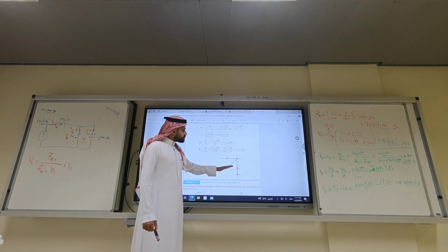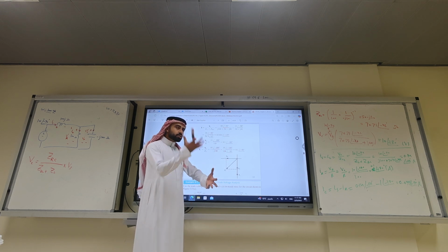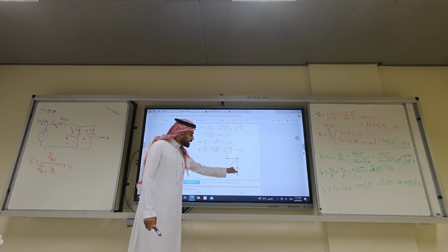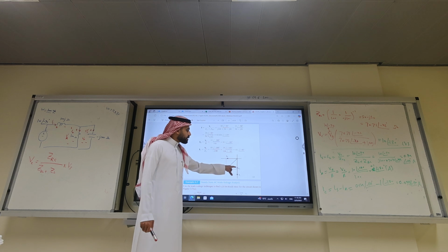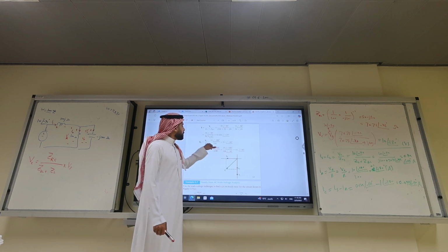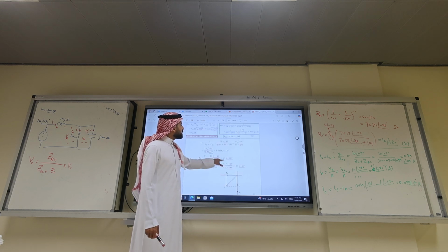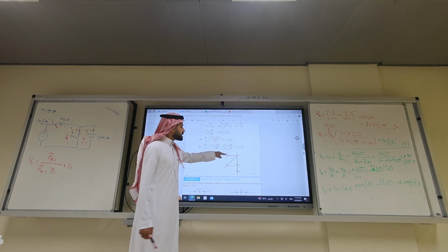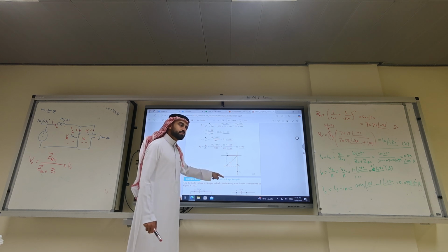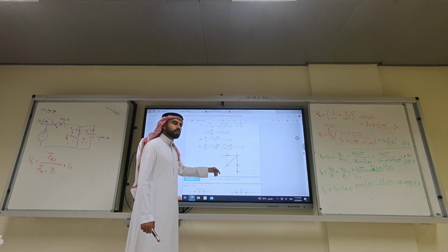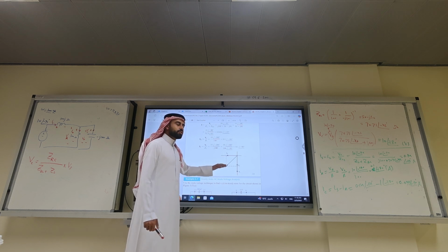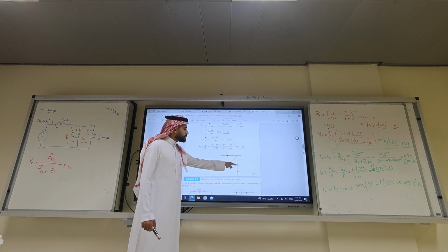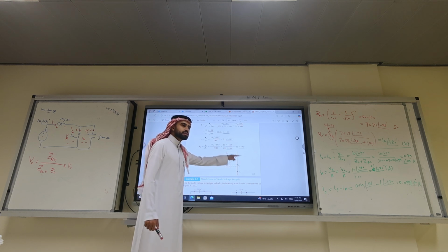The meaning is, again, you compare two comparable values like VC and IC. So VC is not plotted here, but the right way is to say IC is at angle what? Minus 90, but what is VC? VC is at angle minus 180. So VC is here, IC is here. This means what? Means current is leading the voltage. IC is leading VC.